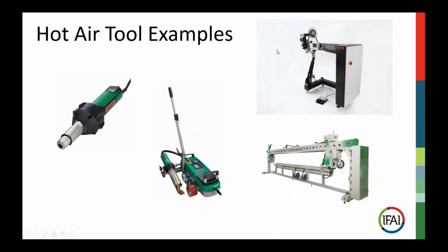And even more advanced than, say, a stationary welder like the sewing machine style will be a large traveling head welder or a multiple head welder, where in some instances you'd have derailleurs, unwinders that manage the material through the process to a point where you really only need an operator to start and end the process on an HMI screen.